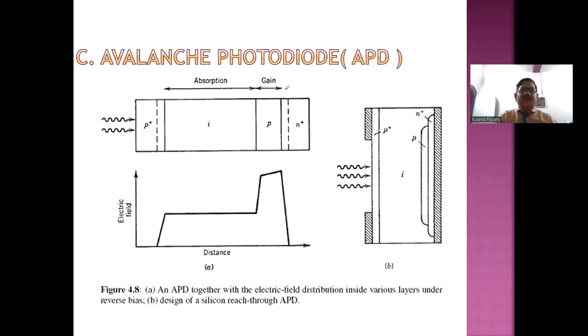Now, how have you restructured here? Instead of taking a simple p-type semiconductor, we have used a heavily doped p-type semiconductor. Similarly, on this side we have taken a heavily doped n-type semiconductor. Then this is another extra layer, which is a p-type semiconductor. So intentionally, I have formed a junction between this moderately doped p-type semiconductor and this heavily doped n-type semiconductor.